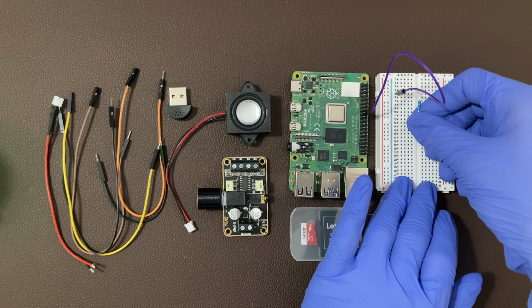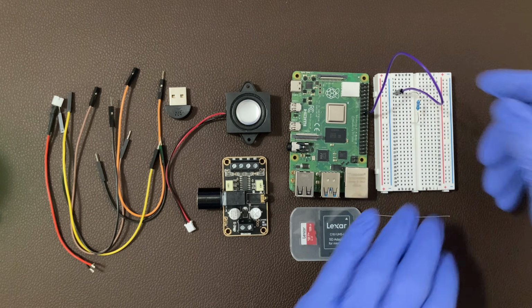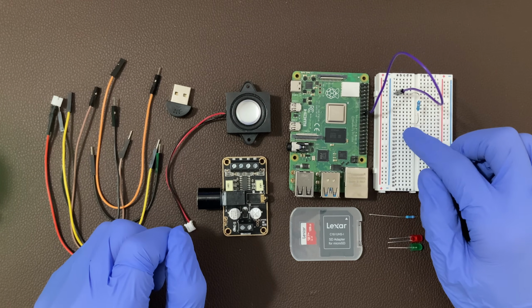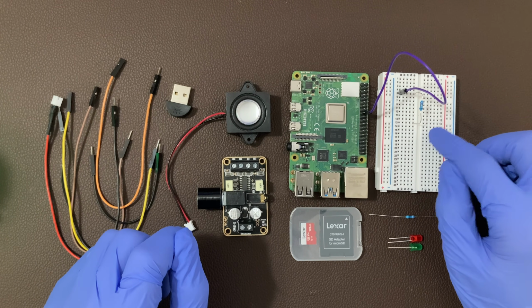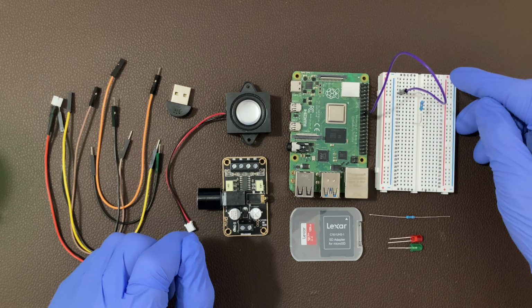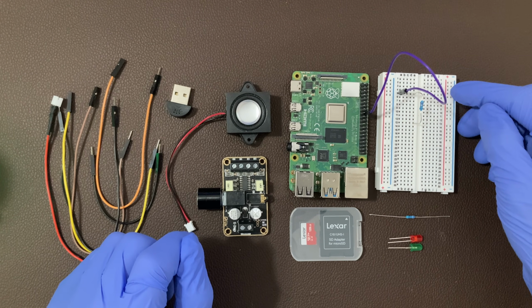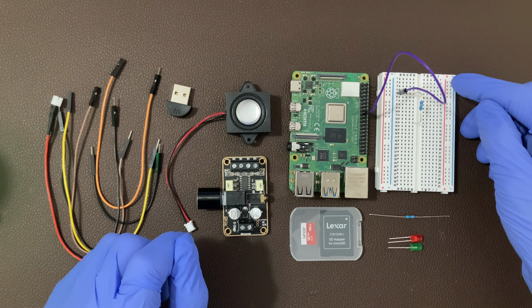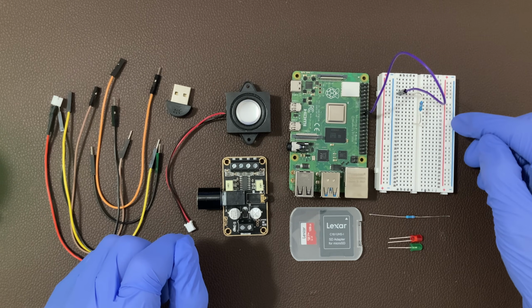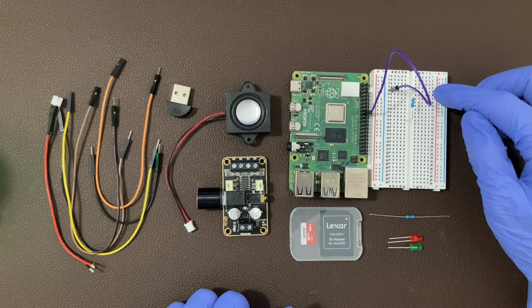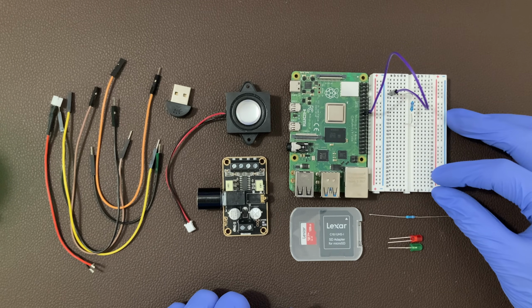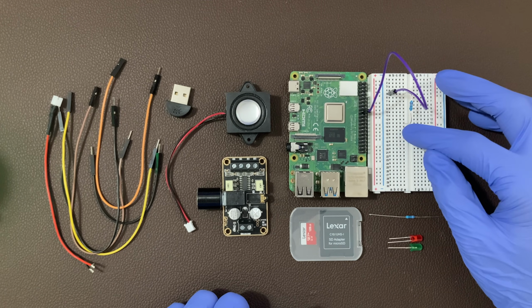A quick note about the breadboard is that if you can see over here on the breadboard, there are 5 pins on a row here. So these 5 pins, they are connected underneath. And the other 5 pins over here are connected underneath here. And then the pins over here are for the power source. You can see here everything next to this blue line here is connected. All the pins along this red line over here are connected underneath as well.